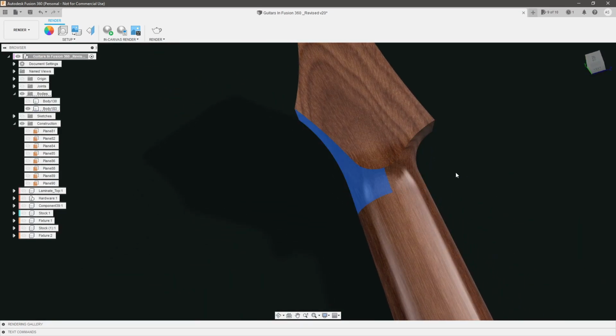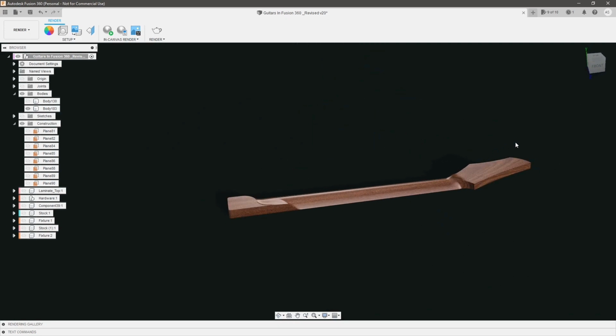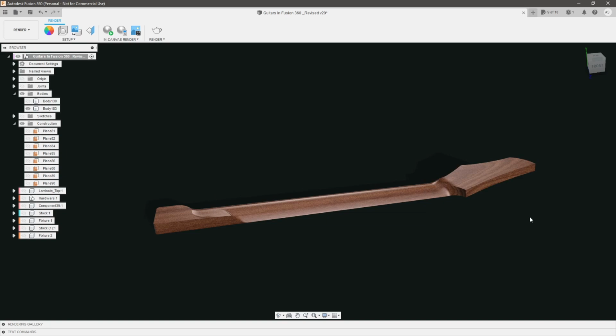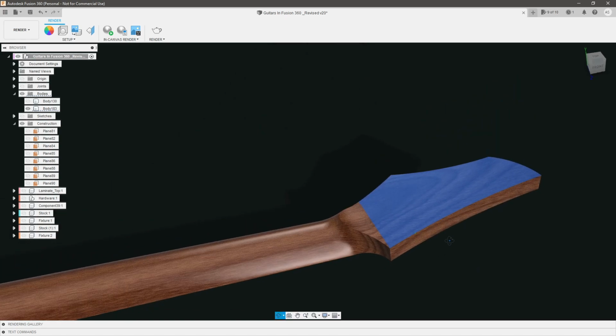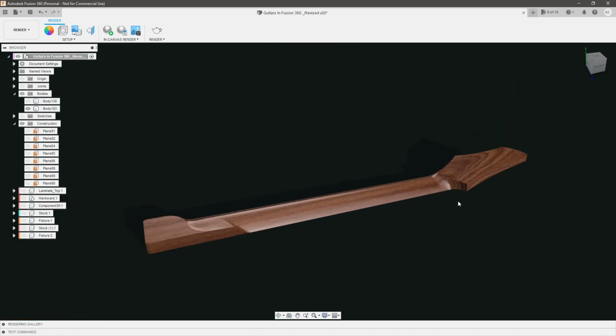So we didn't have to mirror anything over, and we were able to do it in fewer steps without the use of intersection curve. Like I said before, I actually still really love the intersection curve technique, but understanding how that worked, we were able to replicate the same results without having to go overly critical with our sketches in order to make that work. We just simply extruded some surfaces up, split those surfaces with our original sketches, and effectively we did the same thing in fewer steps. So I hope this helps you guys understand how I developed the sketches, and I hope this method helps those of you who are struggling with modeling your designs to get a better result.